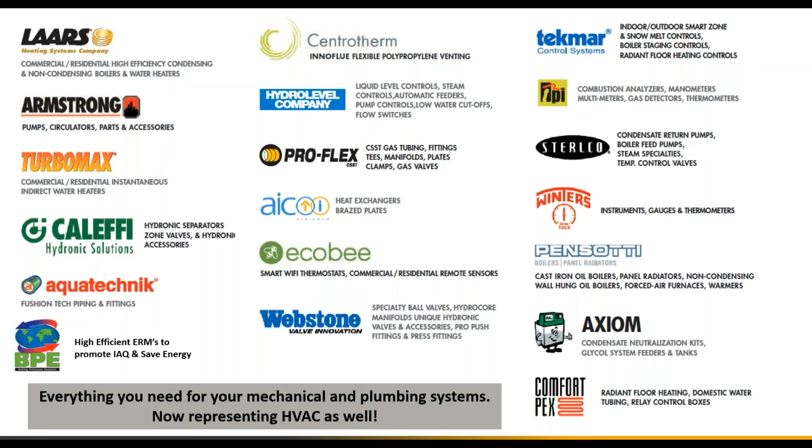Find out from the customer, property manager, somebody, if during the heating season there have been any cold spots. Make sure the system is balanced. Find out if there are any pain points they've experienced with the existing system, especially from a system standpoint. Especially on a commercial application it might be a little more challenging, but get an understanding of what their return temperatures have been in the past.